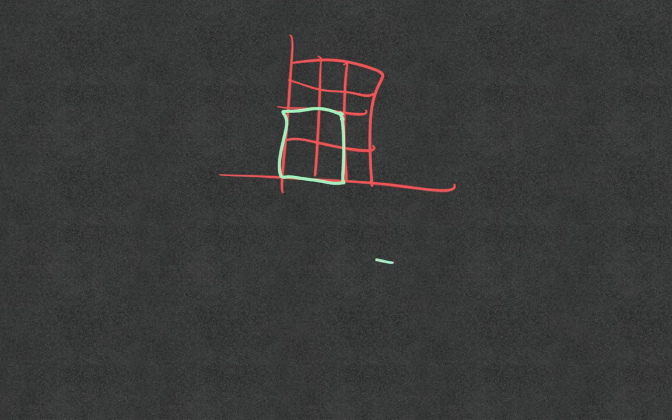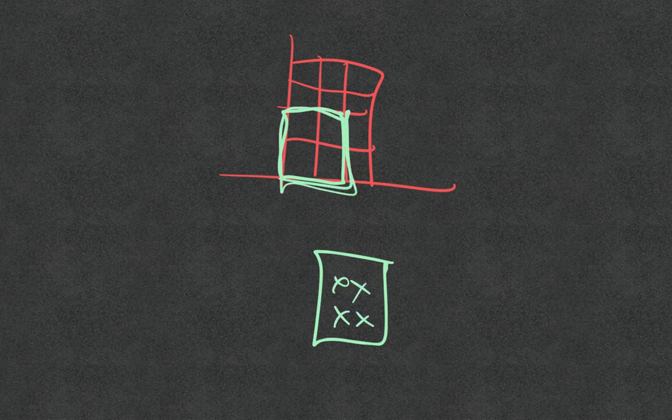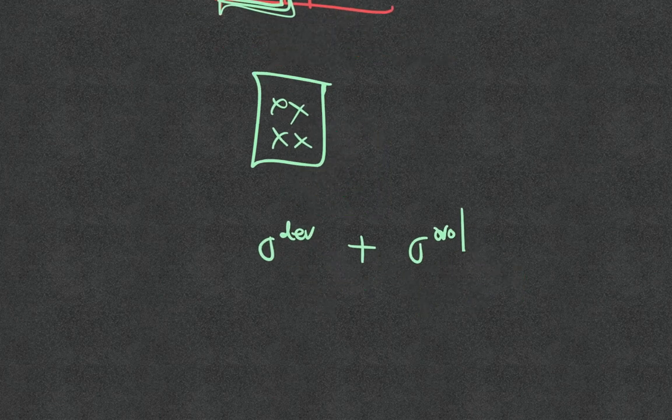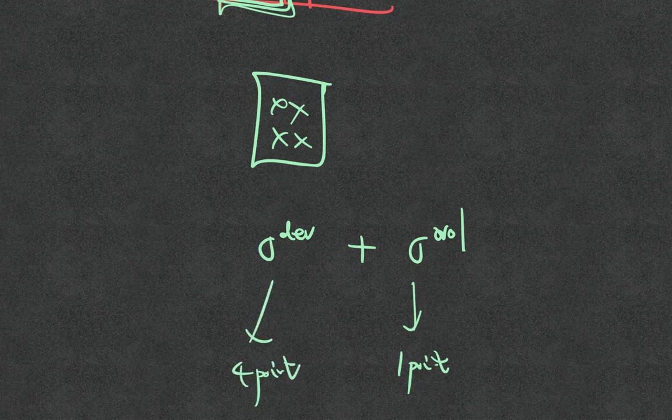Another very common case comes from manipulating the Gaussian quadrature points. This is very much related to this trick. What it does is the following. I have the deviatoric stress, and I also have a volumetric stress. I calculate them separately, and when I integrate the material, I simply integrate this with a 1-point quadrature, and then this one with 4 points. This is a common trick, mentioned in Professor Tom Hughes's book. Now, why would that work?